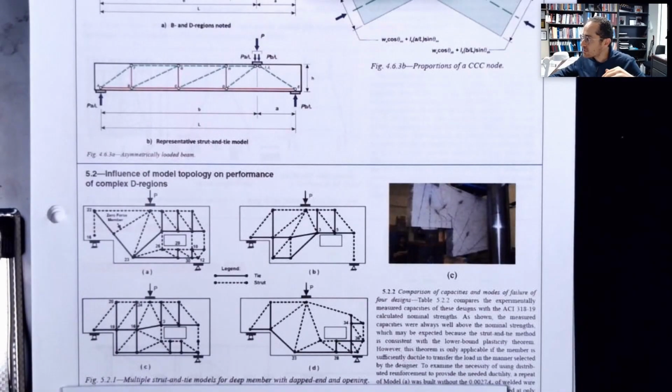If you design this one, it's going to be super easy. You are just going to be laying some horizontal reinforcement. Yes, it would change elevation a little bit, which is fine. You would add another layer of reinforcement here, perfect, and some stirrups in this region and in that region. So in terms of practical applicability, this model is pretty realistic.